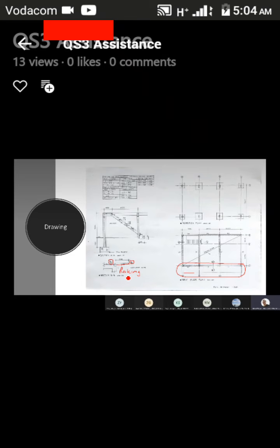So when I look at my cantilever slab, it will then be reinforced concrete 20 MPa 19 millimeter stone in slabs, beams, and inverted beams. Same description that I've had previously for my slab. And multiply by the depth, the thickness of 0.13. But you might say, but sir, where do you get 0.13 from?